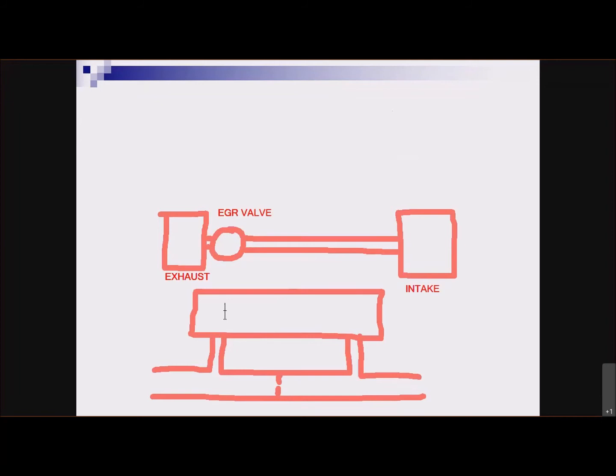So it was called a DPFE, which was either differential pressure feedback EGR or delta, which kind of means the same thing, right? Measuring the difference in the pressure in this passage here, right? This one and this passage here.